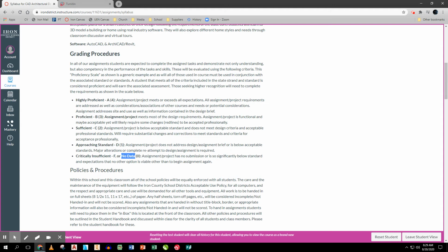You pull from the culture of the area, you address the site, you have the landscaping, the buildings, finishes, and textures that work and go into that right location. You see the historical reference to the design. Like, if you do a Spanish colonial, you understand and can illustrate in your design the reason why barrel tiles are used, why the floor plan is laid out in a formal manner where all of the private areas are to one side of the house and all of the public areas are to the other side. And you understand why that courtyard works and what a casita does if you have one.